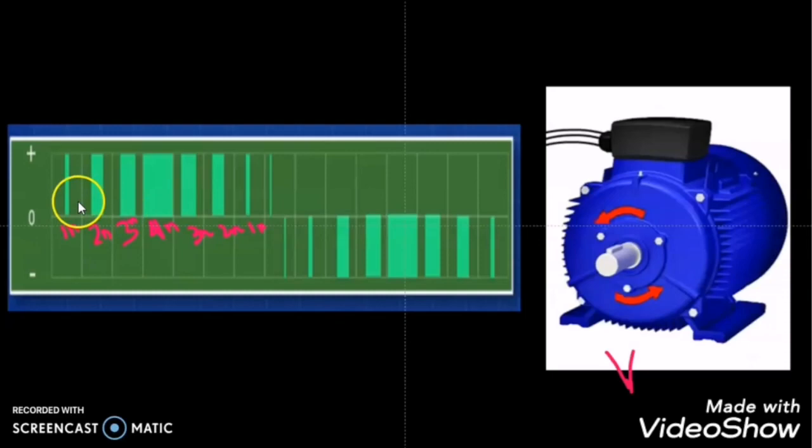So when we try to get the average of this voltage, we will find that when the duration for the IGBT on is less, we will get less voltage, and when the duration for the IGBT on is more, then the average voltage will be comparatively high. So by changing the IGBT switching time duration, we can control the voltage magnitude across the terminal of the motor.